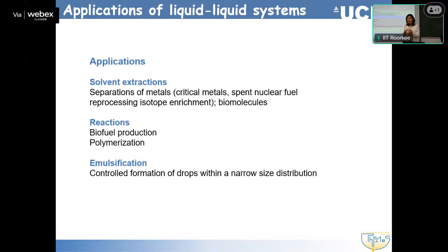It's just that in that case, your conditions are better controlled because along the channel, all your material will experience the same transformation, while in a stirred vessel, because of the non-homogeneity of the flow in the mixing, you may have different regions having different conditions.